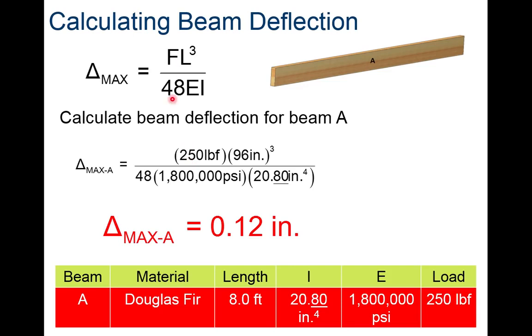We will have some force. Go ahead and write your equation and then start substituting and solving. Some force, in this case 250 pounds of force. This is, again, has to be right in the middle to use this equation. Length is in inches. Please make a note off to the side. Length has to be in inches. Commonly these beams are given as an 8-foot beam. It's not given in inches, so length has to be in inches. Also, while we're here, it would not be a bad idea, again like we did before, FL cubed. It's not FL and then cubed that product, just L cubed.